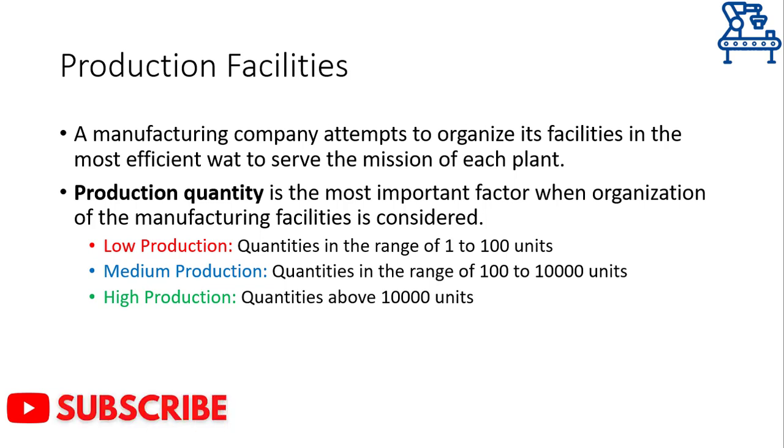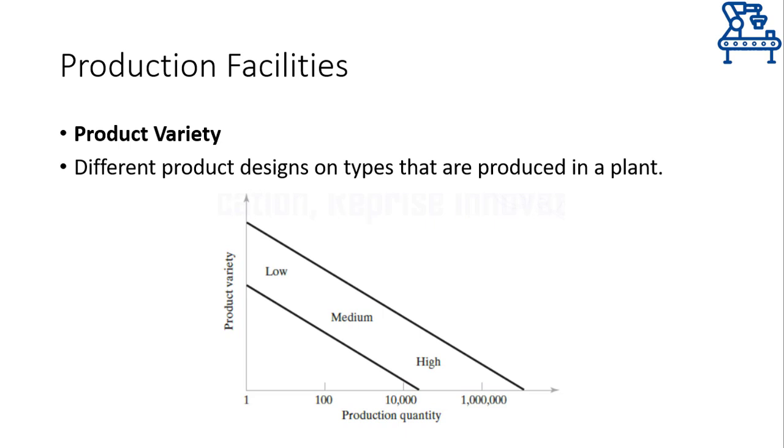Generally, low production doesn't motivate fully automated systems, whereas high production is not achievable via manual labor. Furthermore, low production quantities mean you can have high production variety because it's easy to change the manufacturing system when few units are being produced. And if human labor is used, then exploiting the dexterity of human workers, industry may incorporate variety in the products quite easily. However, the same is not true for high production quantities. First of all, humans are not capable of producing large quantities, and secondly, dedicated automated systems are specialized to produce low variety or technically called soft variety products.